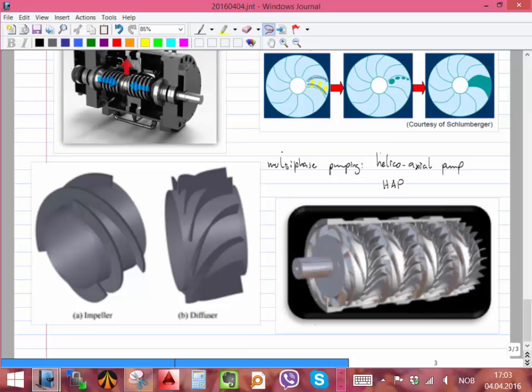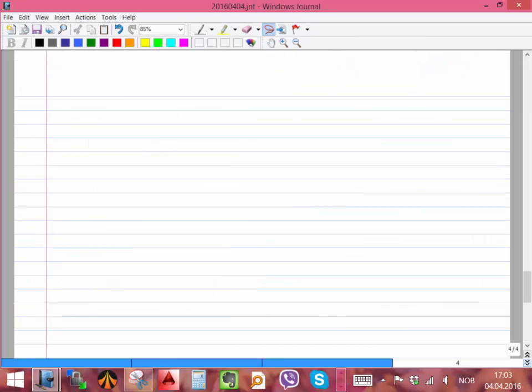When it's multi-phase, it's not clear. Let's say in the case of the pump, the delta P, what is the performance plot of the pump? Delta P versus Q, and it looks like that. Everything in our course is either like this or like that. Not to generalize, but it's roughly the truth. But if we add a little bit of gas, the gas is disturbing very much the dynamics of the machine.